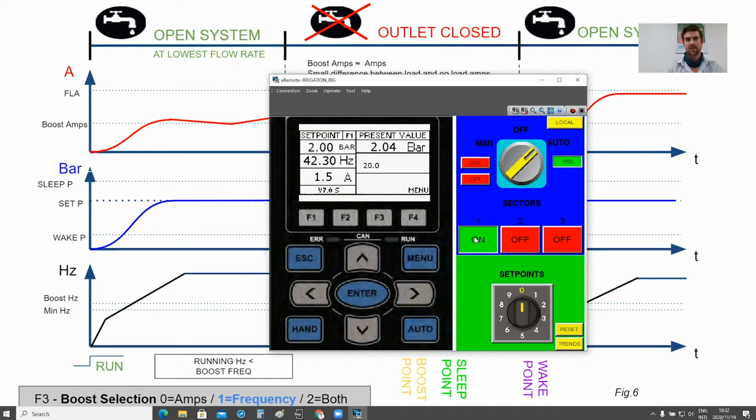All right, so if I disable the last valve, water has nowhere to go. I'm pumping up against a closed valve now. My amps drop to 1.4, which is below my 1.5 mark. And now the system starts to time out. So this gives you a nice visual to note how the dynamics of your system are operating.